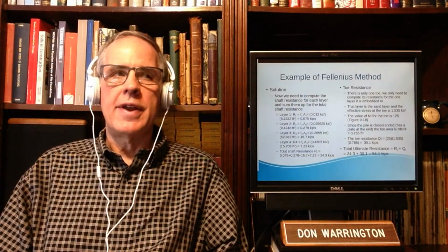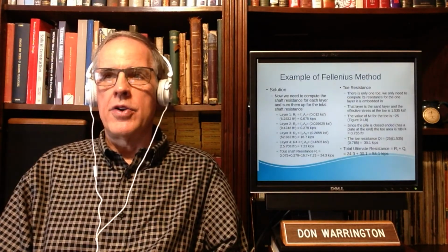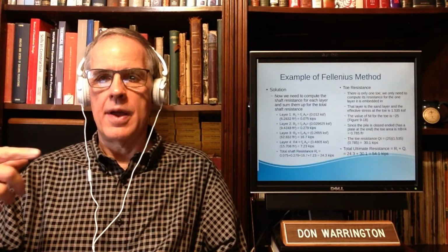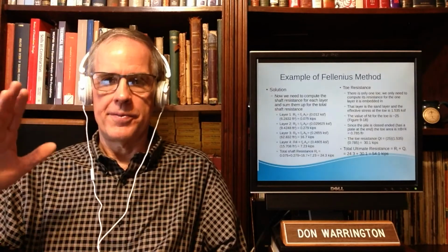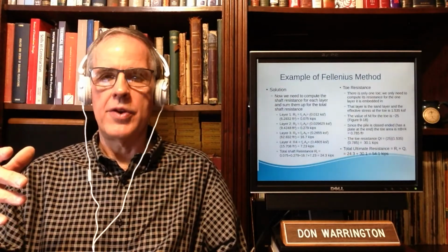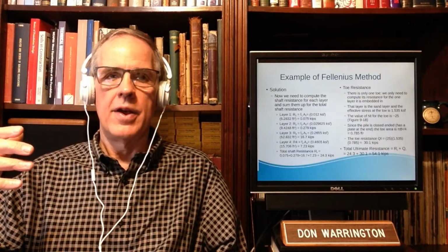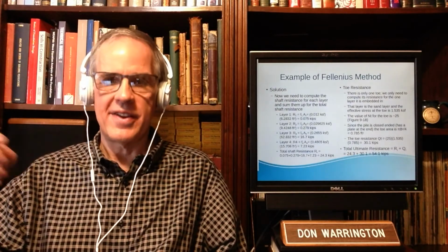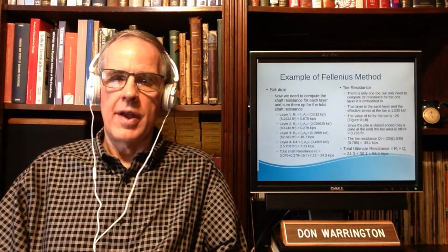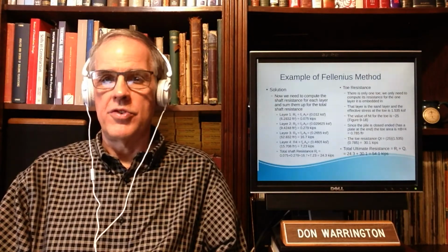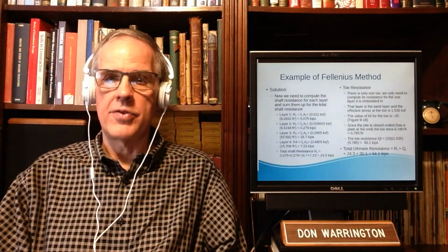Unless you're doing stuff like drivability studies, where you need to have a progressive pile resistance that progressively increases as you go in the ground. You don't really need to do that. Just one toe resistance, and if you're doing a full penetration of the pile.